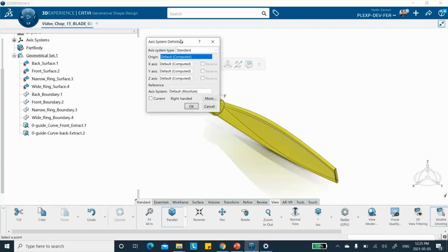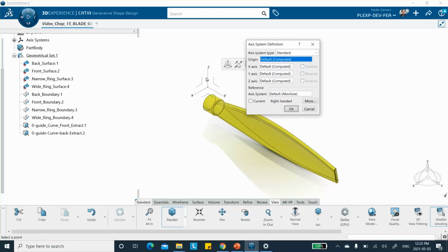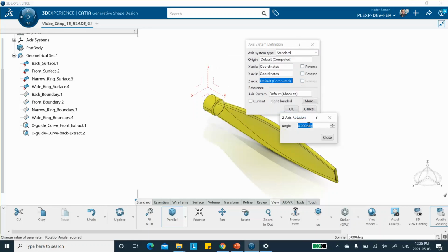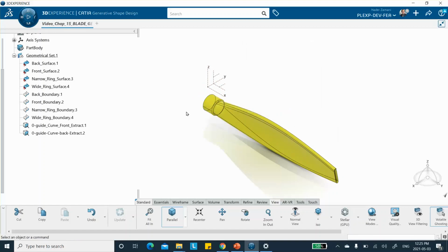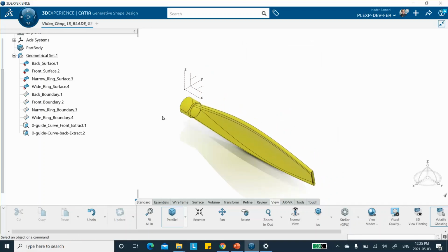Okay, I'm going to rotate this thing about Z axis by 90 degrees. So put the cursor there, right click, rotate about the Z by 90 degrees, and I'm pretty sure that will place the X along the axis of the blade. Okay, good. Now remember, the global coordinate system X is actually this way, and later on when the propeller rotates, we're going to be rotating it about the global X-axis, not this axis.